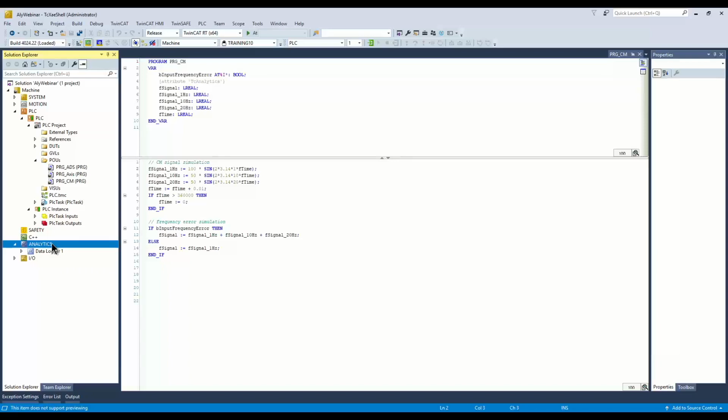It's just delivered with TwinCAT if you have a version higher than, I think, 4022.31. It's available and you can use it because it's integrated as a so-called TcCOM object in the background. So if you integrate this logger, no installation is necessary. It's just configurable. You can edit it and you have to activate your configuration. So you have to touch your running system for sure, but no installation is necessary. You can easily integrate it.